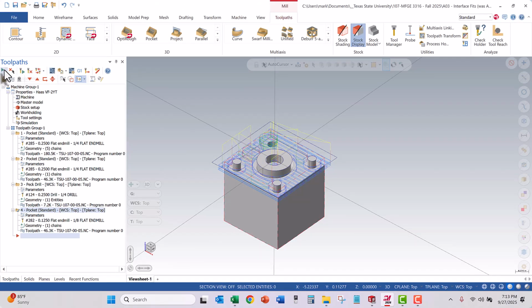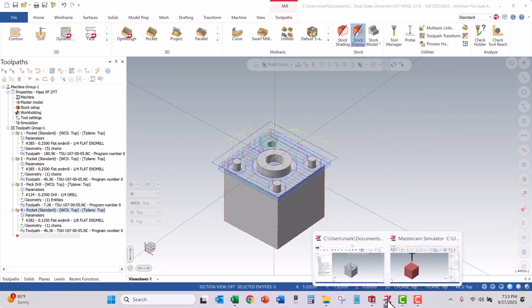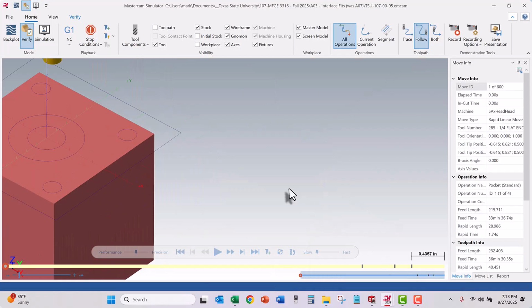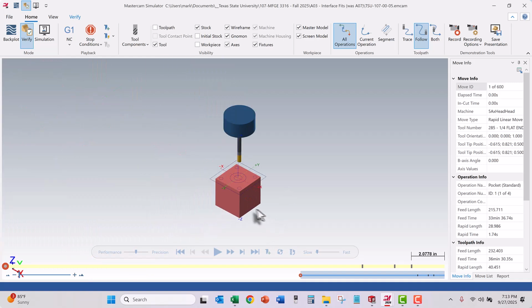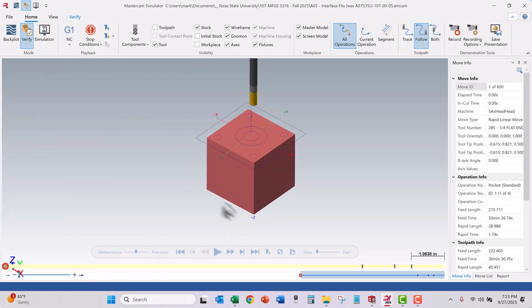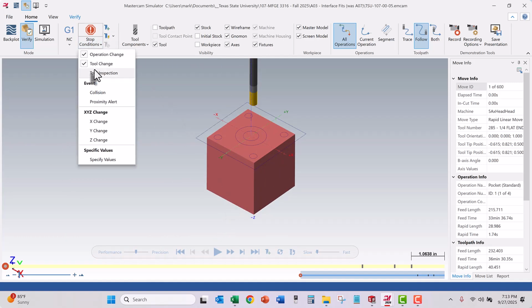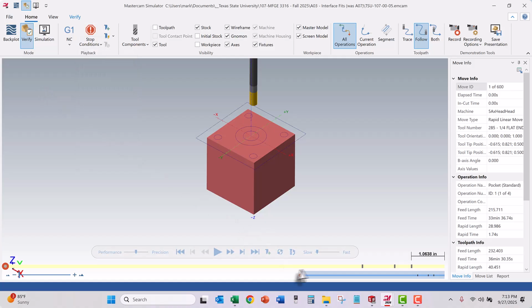simulation. So I'm going to select all tool, select all operations. So now I got a checkbox. See the little checkbox next to all 4 of them? I want to see the simulation of all 4 of them. I'm going to click this button right here that says verify selected operations. And what happened to my window? Here we go. So now it's sitting waiting to play it for me. These settings I assume are still the same. Yep. I'm going to slow it down nicely here.